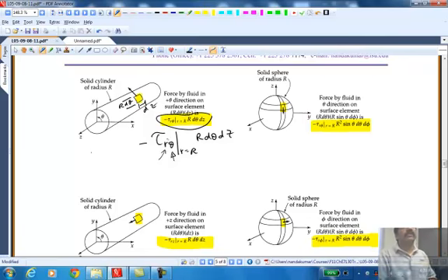An expression like this is the one that's going to get you an answer to that, because it says I'm calculating tau r theta on the R surface. Now in this case I'm calculating theta. What does that mean? I'm calculating the force that is tangential to the cylindrical surface. There is also a tau r r on the same surface.